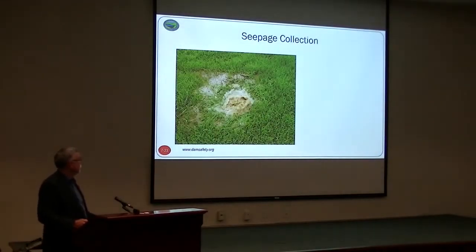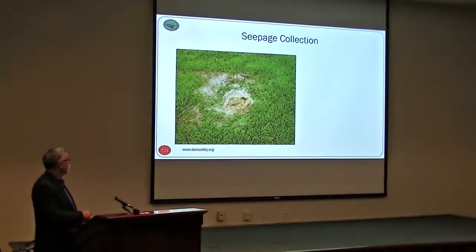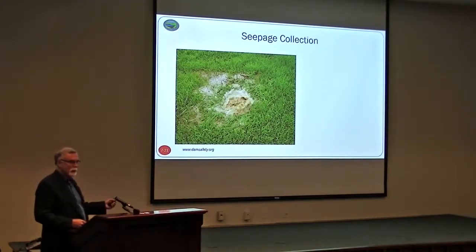Talk about seepage. Here's another example of a boil. Obviously, if you're doing an inspection, you're going to see that. You see the muddy water. That's a level 2 of an EAP. You see that.